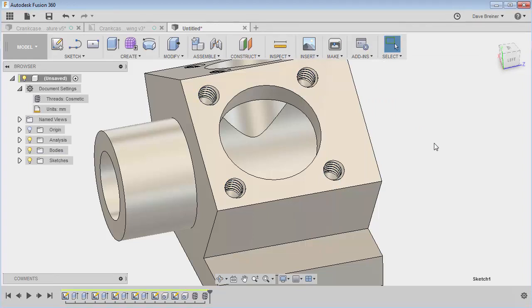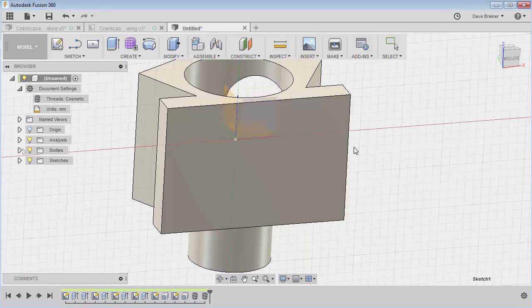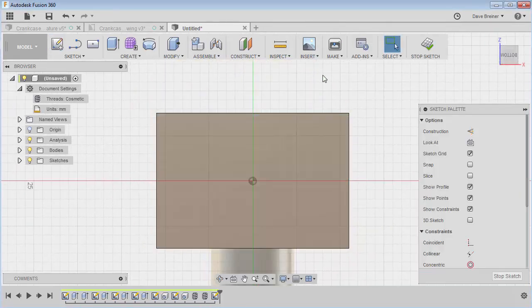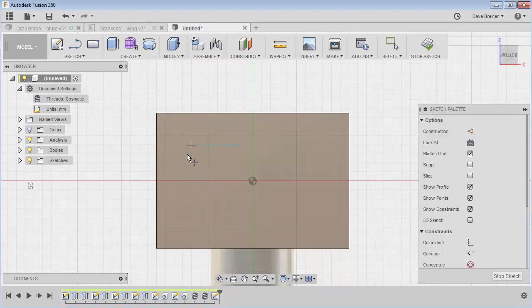Okay, I think one of the last things we have to do is the 2 holes on the bottom. So let's place a sketch, and I'm going to place a sketch again on that bottom face. I'm going to place 2 points, and you can see here's a perfect example why I want to hold the control key, because it's trying to do a soft constraint on a lot of geometry. So if I hold control, you're going to see that now that doesn't persist. All right, so I'm just going to place 2 points,